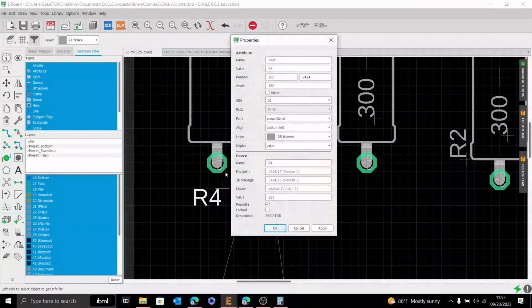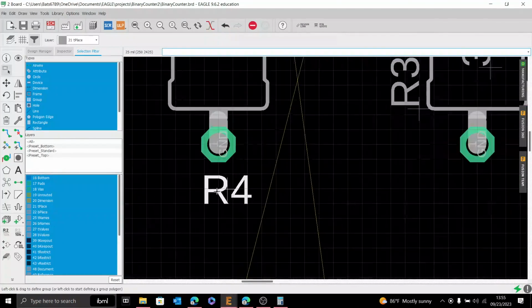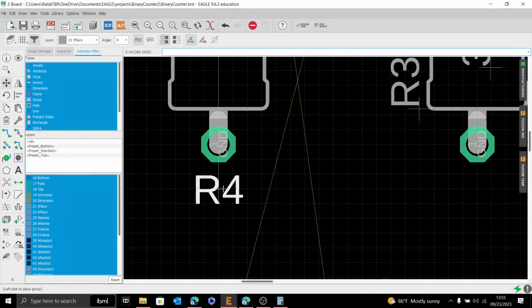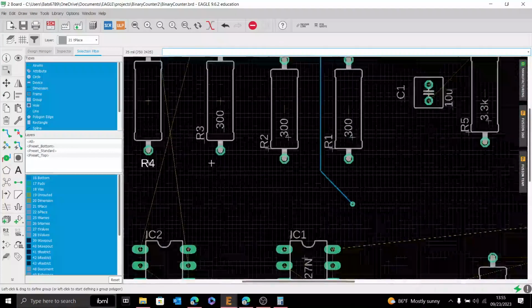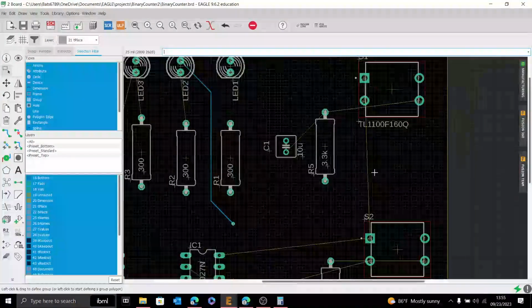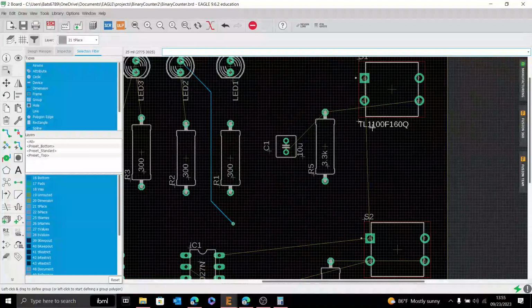select info, and you notice how that is offset to the crosshair? If we click on this align, you have some different centering options or alignment options for your text. So I'm going to do center center so that wherever this crosshair is, I know my text will be centered. That comes in handy in case you change your mind and want to change it later.